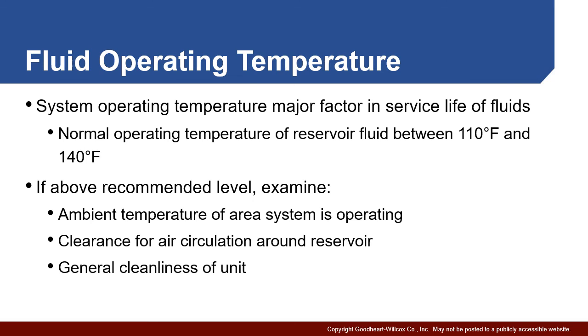If it's a hot environment, you may need to cool it off in some way, air conditioning, fans, etc. Keep in mind that the reservoir itself is designed to transfer heat, so you want to make sure that it is relatively clear and air movement occurs around the reservoir. The other thing about it is as dirt, dust, etc. builds up on the unit, that acts as insulation and prevents heat from transferring away from it as well. So all those things are things to be looked at if you are having trouble keeping the temperature down in your hydraulic system.